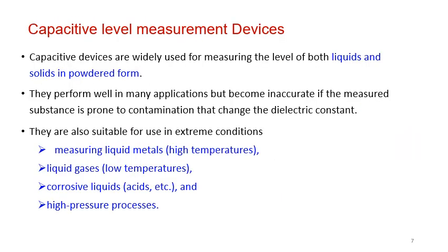A capacitive level measurement device is a device which can measure the level of liquid or even solid, but in powder form. What basic principle are we going to use to measure the level by capacitive type? If this is the capacitor, of course one of the elements which will decide the capacitance of the capacitor is the dielectric material between the two plates.